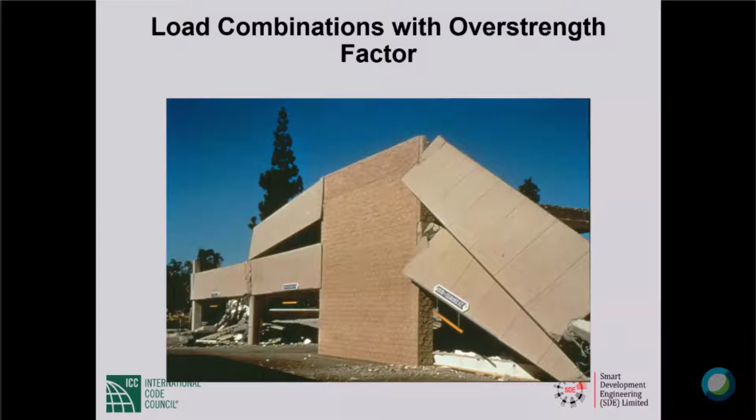And the reason became apparent pretty quickly. The shear wall looked that good because it didn't have to do anything through the earthquake. The collector elements that were supposed to take forces to the shear wall that would have made it work failed before the force transfer took place. Okay. And if you don't have to do anything, it is easy to look good. All of us know that.